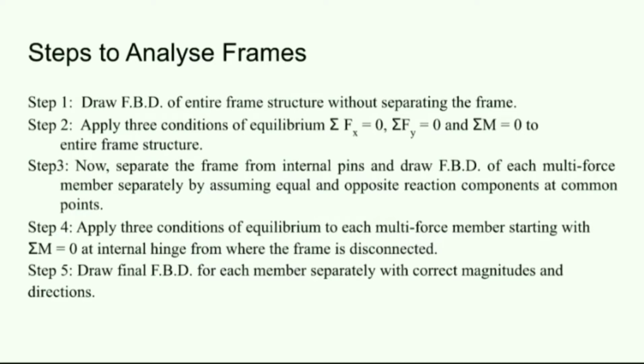In the next step, we need to isolate the frame which is connected at the internal pins and draw the free body diagram of each multi-force member separately by assuming equal and opposite reaction components at the common points. Next, we have to apply all three conditions of equilibrium to each multi-force member, starting with summation of moment equal to 0 at the point through which it is connected, that is at the internal pins or internal hinge.